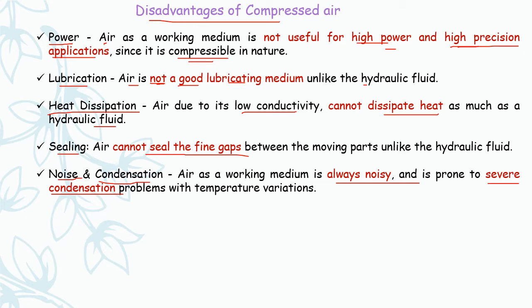If air is the working medium, your pneumatic systems are always noisy. When you compare it with the hydraulic system, they are lower, they don't make much noise. So here pneumatic systems are always noisy and are mainly prone to severe condensation problems if there are any temperature variations in the system. So this is about advantages and disadvantages of compressed air.